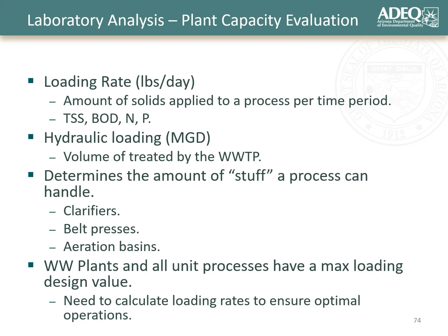The reason why this is important, number one, the hydraulic loading rate, I think, is pretty apparent. You push too much water through your system, you can cause all sorts of issues in terms of a much shorter reaction time in your systems. You can wash out areas. You can also overflow weirs or even overflow structures. And that is clearly not something that is ideal. But the loading rate is ultimately determining what the capacity of your plant is to be able to treat a certain pound of material.